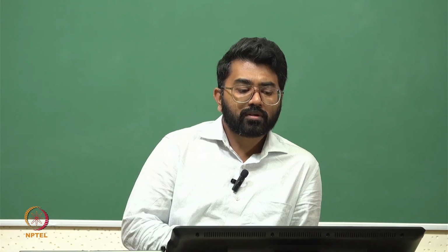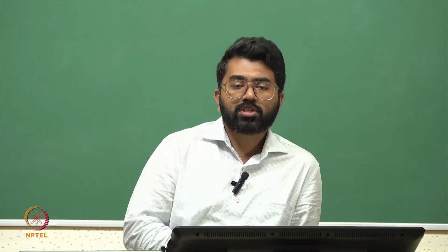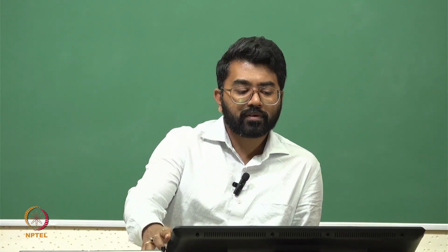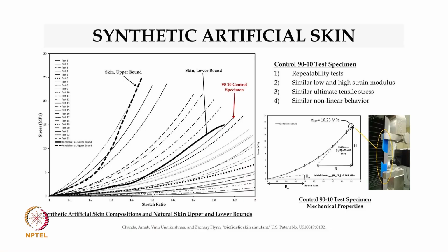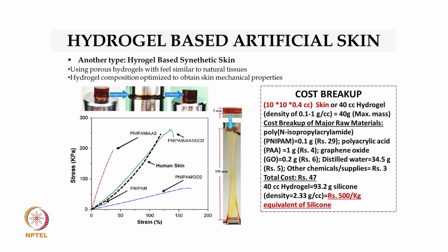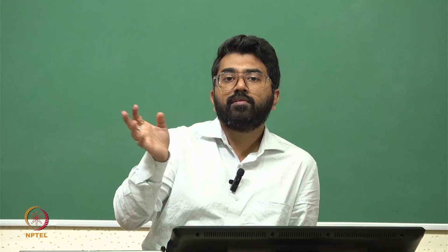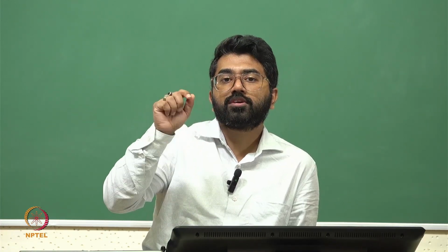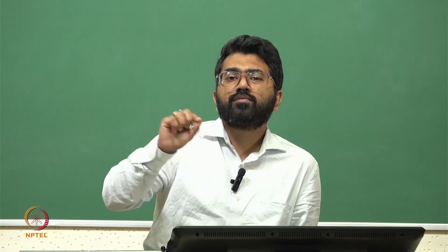But one thing to note here, the overall property of this material was much lower than what we observed previously. Here you're looking at a stress of 20 or 25 megapascals, and here you're just looking at 200 kilopascals, which is fairly low. So you are playing in a small range. If you remember, most of the in vivo techniques, like indentation and imaging, give you the force displacement or stress strain in a very small range or with small loads. That's the same case with these hydrogels, right? We could not test them or operate them at a very high load.